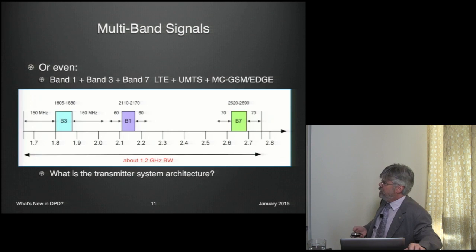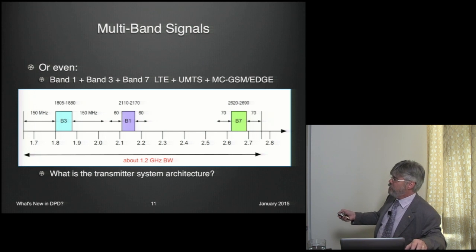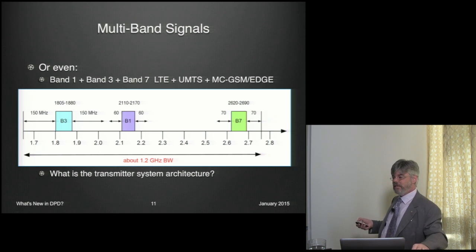If that's not bad enough, we're also getting asked this, band 1, 3 and band 7 for frequency domain LTE. Again, there might be multi-protocol in these. This is an LTE band, but now you're talking double the bandwidth to accommodate these. And then, of course, you've got the intermod products between this clump and this clump of energy dropping more signals around here. And who knows what's in here? Some other users are around that part. So this is a real challenge. You know, if 600 megahertz was hard, this is more than twice as hard, believe me.